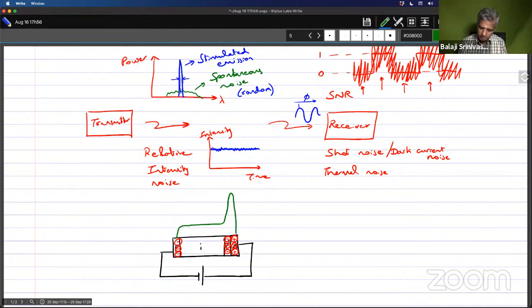And in this region, there will be a fairly high voltage drop because you have a sudden change in the charge density from negative to positive. Okay, so there will be a very large field over here. And if that field is beyond a certain threshold for this impact ionization process, then what happens is you have these charges,